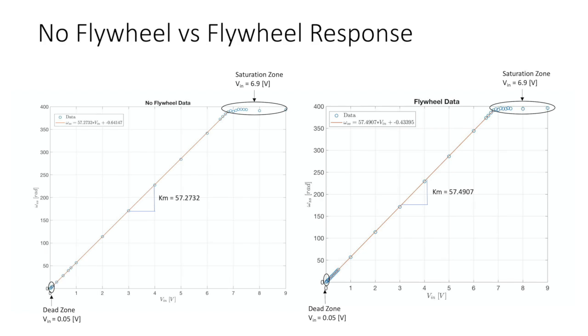It is important to use only the data in the linear portions of this plot for doing the linear regression to find this slope, as the nonlinearities in the dead zone and saturation zones can cause bad performance due to friction or inductance of the motor.